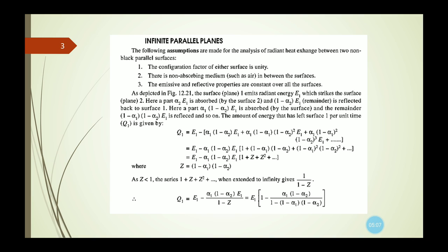There is a non-absorbing medium such as air in between the surfaces. And the emissive and reflective properties are constant over all the surfaces. These are the three assumptions that we take in the case of radiant heat exchange between two infinite non-black parallel surfaces.